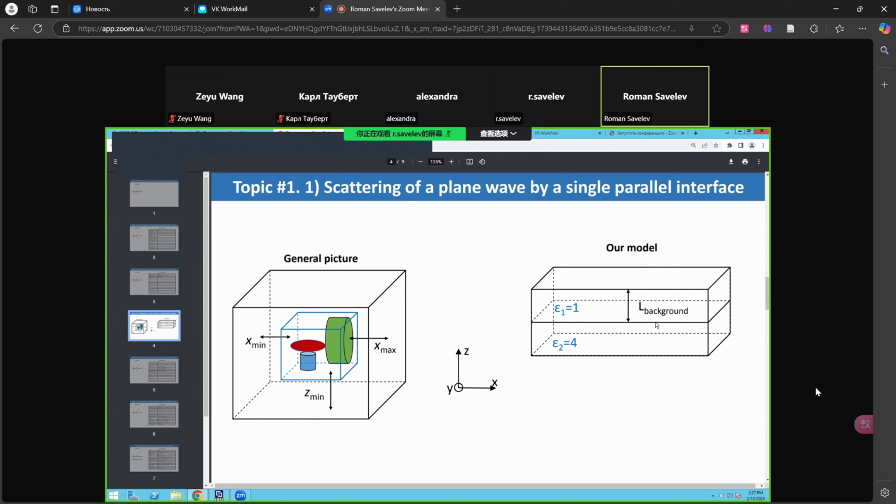Then you get additional losses in your system, which shouldn't be there. Near fields are not associated with losses in the system. This is just the energy stored in the near fields near the structure. So in these problems, you need to put the boundary away from the objects to make sure that the near fields decay enough.